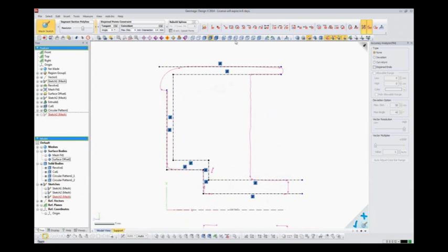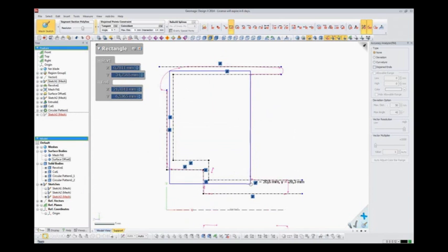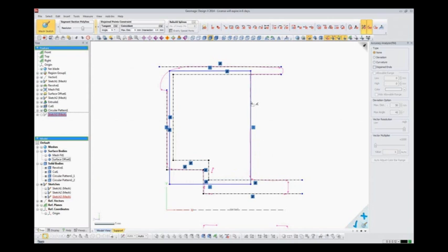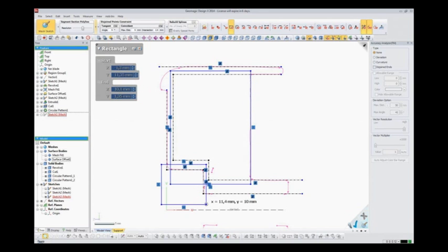Make them a construction geometry, and then I can start doing this inner stuff. So now it would be useful to have the fillet first, because here we are peeking out of that area, but it's not a problem now because we have a little bit more material here. So in this case I want to get rid of this edge as well, so I'm using power trim.